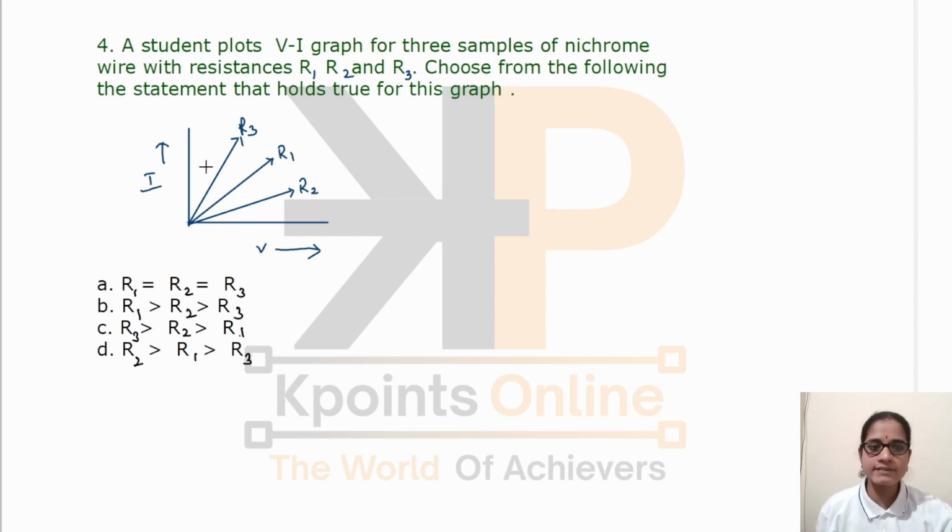The next question is, a student plots a VI graph for three samples of nichrome wire with resistances R1, R2 and R3. Choose from the following the statement that holds true for this graph. Here the graph of I along the y axis and V along the x axis is given. What does the slope of this graph give us? The slope is equal to I upon V.